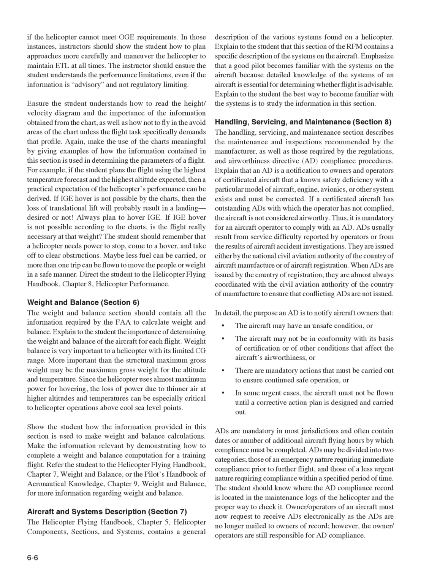ADs usually result from service difficulty reported by operators or from the results of aircraft accident investigations. They are issued either by the National Civil Aviation Authority of the country of aircraft manufacture or of aircraft registration. When ADs are issued by the country of registration, they are almost always coordinated with the Civil Aviation Authority of the country of manufacture to ensure that conflicting ADs are not issued.